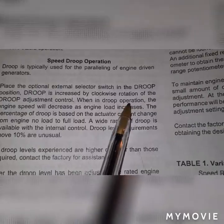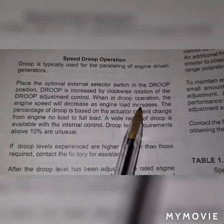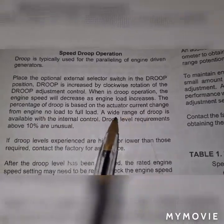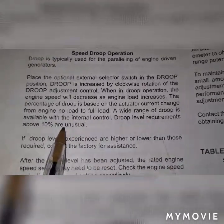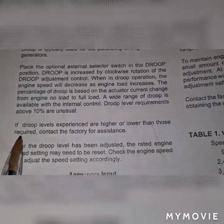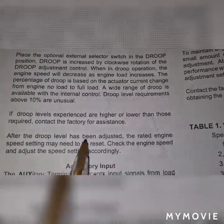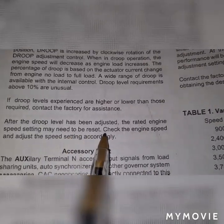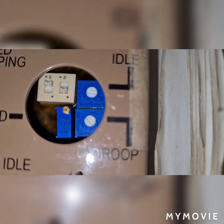When in droop operation, the engine speed will decrease as engine load increases. Okay? The percentage of droop is based on the actuator current change from engine no load to full load. A wide range of droop is available with the internal control. Droop levels above 10% are unusual. If droop level requirements are higher or lower than those available, contact the factory for assistance. After the droop level has been adjusted, the rated engine speed setting may need to be reset. Check the engine speed and adjust the speed setting accordingly. So that is the use of our droop.